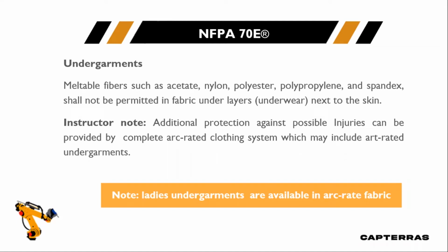As an instructor note, additional protection against possible injuries can be provided by a complete arc-rated clothing system, which may include arc-rated undergarments. And another note for women: ladies' undergarments are available in arc-rated fabric.